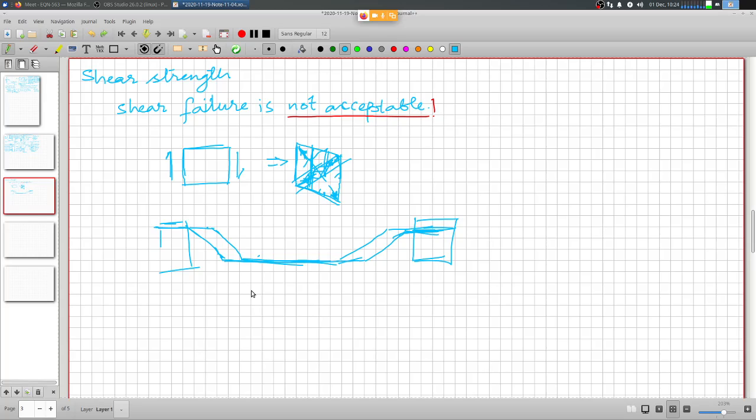If you look at the stirrups, they only intersect the diagonal tension at an angle, so the full steel section is not completely used. Only a fraction is used, and it is more of a dowel action.